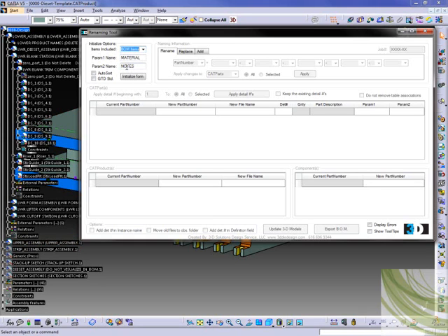Next we have two parameters here that are modifiable. We have them set by default to our material and notes parameters, but if you had other parameters you wanted to bring in to be able to review or to modify, you can type them in here and get those. These are all also fully customizable. Last, we have an auto sort option here that you can select on. This will allow you the ability to automatically sort out purchased items versus made items. The GTD standard is something that's an optional thing that we do, but